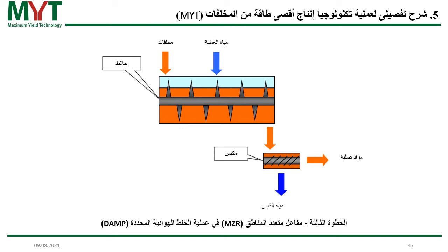After 2 to 3 days of mixing, the waste from the entry of the mixer has passed through until the end of the mixer, and then is pressed. With the press, we separate the solid material from the liquid material. Within the liquid material, we now have all the dissolved organics, where we make biogas out of it.